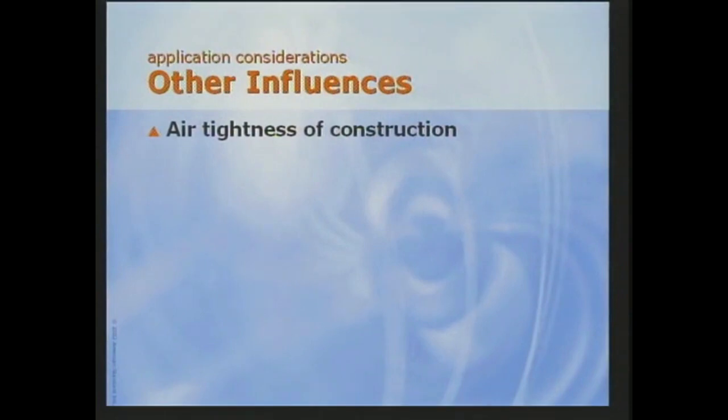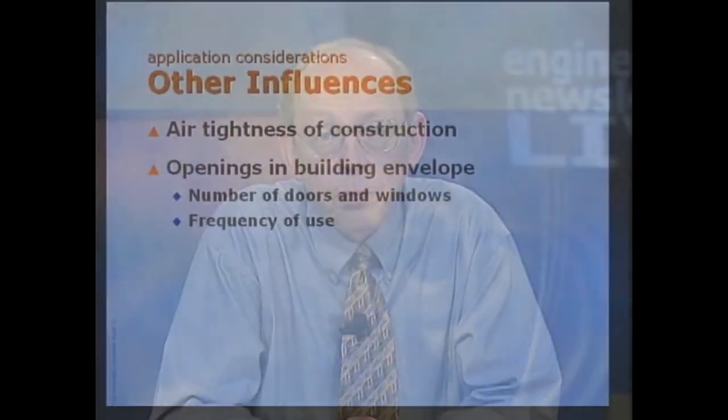First, quality of construction. A poorly constructed, leaky building, it's very difficult to maintain pressure at the desired level. On the other hand, in a well-constructed, tight building, pressure control becomes very important to avoid excessively positive or negative pressure. A well-sealed building saves energy, but makes pressure control a necessity. This is one reason that we think this building pressure broadcast is important.